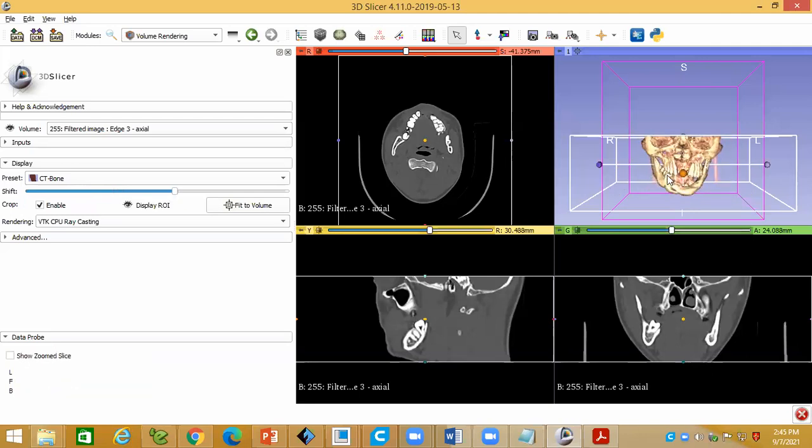Now here you can see this is a bone. My region of interest is the bone, so that's why I'm selecting the bone. Next, I require only this small portion. I don't require this remaining portion. I require only this amount because it is a very big part, and this big part I cannot accommodate in our small 3D printer machine. So that's why I'm removing the unwanted portion.